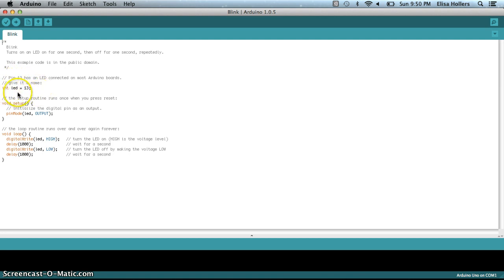And then below we have our first thing, which is a variable of the type integer. Now, we discussed previously what the different data types are and how that works. So we've named it LED, and it's 13. And if we go down here, we'll see that it runs the setup function, which basically allows us to run the program. And we're going to set the pin mode to value 13 and output. So it's going to basically have this 13, which is the port number, and its output is what it's going to set up as.